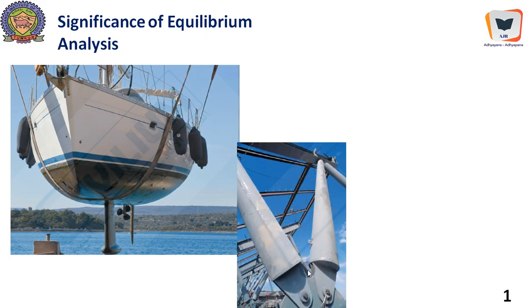The elements of this truss, 1, 2, which is attached over here at this joint, which are conveniently taken to the joint above, transmit concentrated forces to the joints at both ends, and the joints ought to be in equilibrium in order to safely transfer the loads. Otherwise, there will be relative movements between the parts.